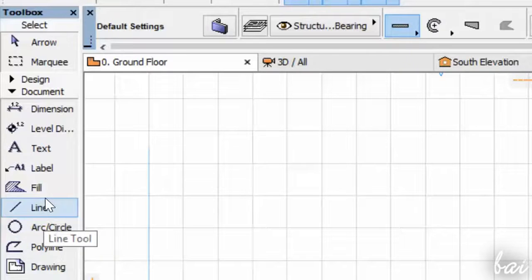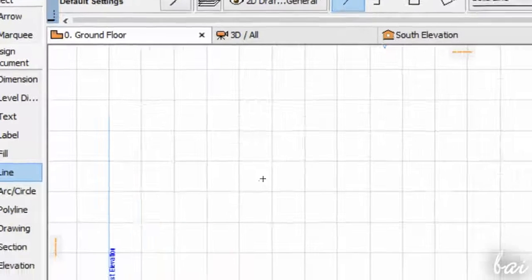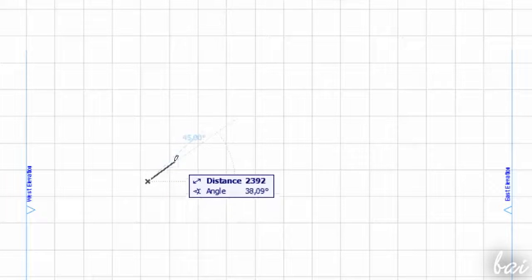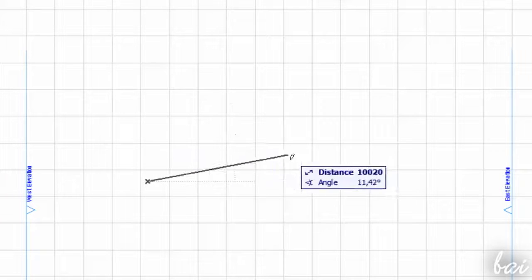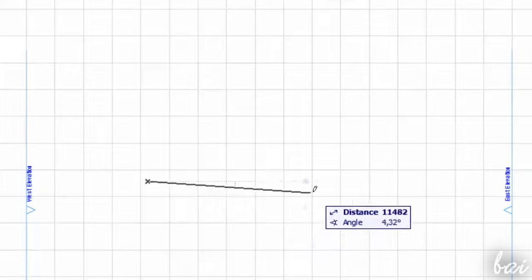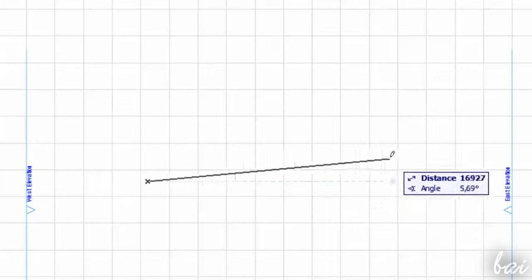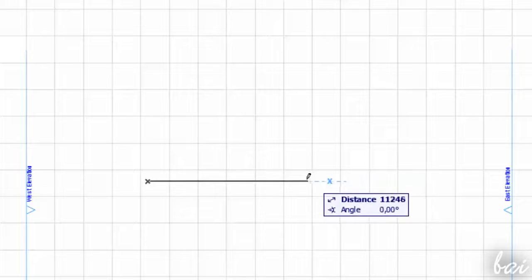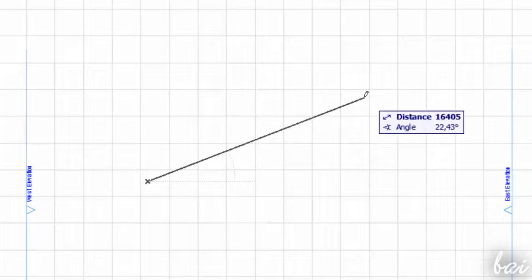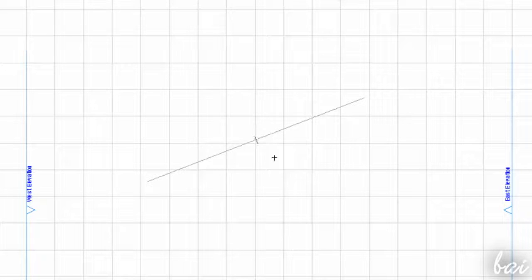with polyline. For example, to draw a line, you must start from a point, called the starting point, fixed by clicking on your workspace. This will be indicated as a bold cross. A preview of the object's shape is shown with a dialog box indicating distance and angle respect to the horizontal direction or x-axis, indicated by a dotted line. When you fix the second point, the segment is done.